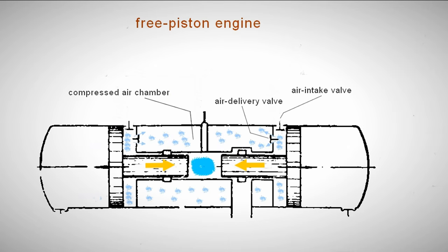At the end of the compression stroke, the air in the compression chamber accumulates and compresses, preparing to scavenge the combustion chamber. The air in the diesel cylinder continues to compress, increasing pressure and temperature. When the air temperature exceeds the auto-ignition temperature of the fuel, it is injected into the cylinder through the injector. The fuel ignites and burns, causing the cylinder pressure to rise sharply to 100 to 130 bar. The engine's power stroke begins, during which the combustion products expand and push the pistons in opposite directions.